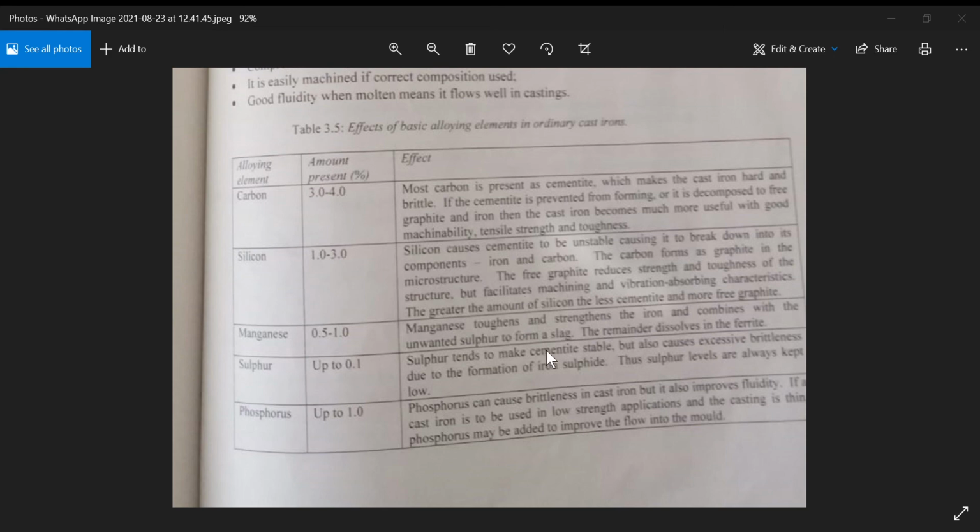Now we'll look at this first before we look at the table. Compacted graphite cast iron, that's this one here. What we notice is that it's still rounded-ish. It's not as sharp as the sharp flakes, but it's not fully rounded. It's in between. So this is most round, this is like half round, half sharp, and then this is really sharp.